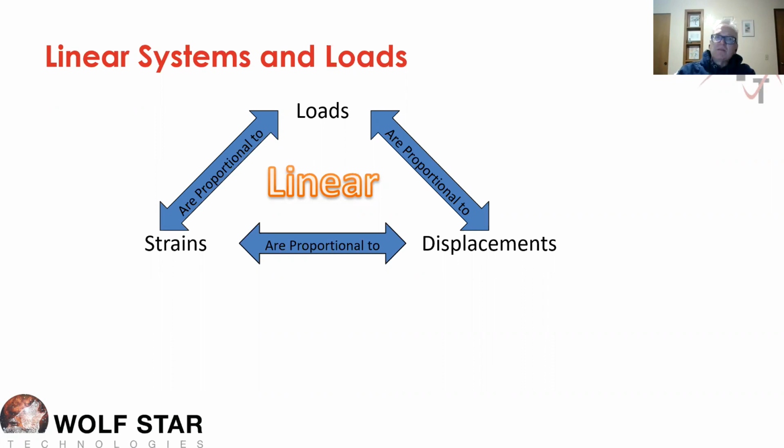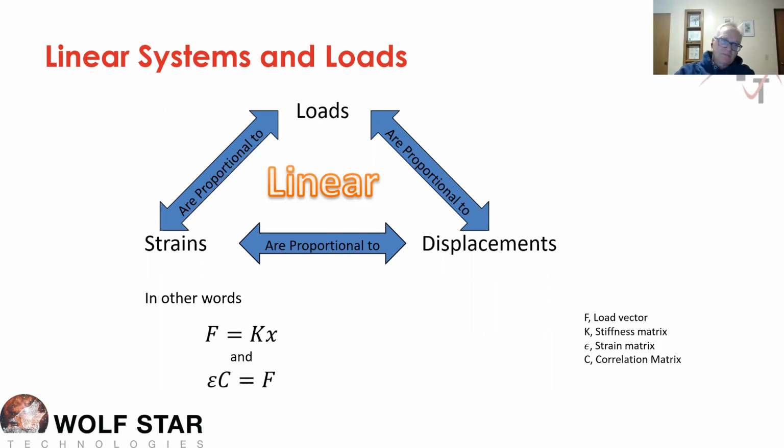The exterior loading can be as nonlinear as anything. It could be ramp loading, sinusoidal loading, impact loading. That doesn't matter. We just need that strain response to remain linear and proportional to the exterior loading. So I can take this little diagram here and turn it into a couple of equations, okay? The right-hand side is just Hooke's law, F equals Kx. So if your structure is obeying Hooke's law on bulk, you can have local plasticity, but if on bulk your structure is obeying Hooke's law, then the left-hand side of the triangle has got to work as well.